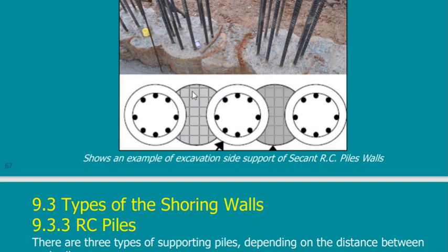So I have this pile, and I have this pile, and another one, and another one, and so on. There is a gap between this first pile and this second pile. And then I bring my machine and drill in between. When I drill in between, I am touching this and touching this. This is a plug, and this is a plug. Water cannot pass here, and water cannot pass here. And then I put my reinforced concrete pile.